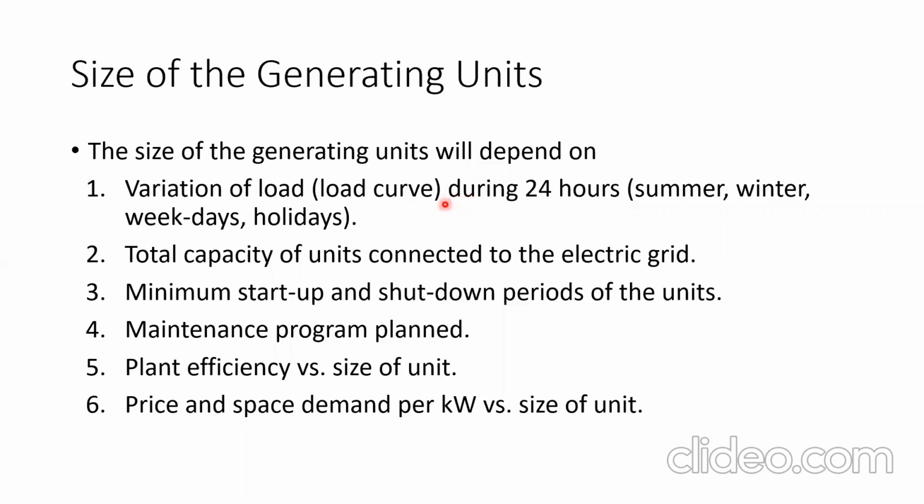According to that, the size of generating units will be selected. And also you have to see what the load curve is in summer, winter, on weekdays, and holidays. All these things you have to consider.